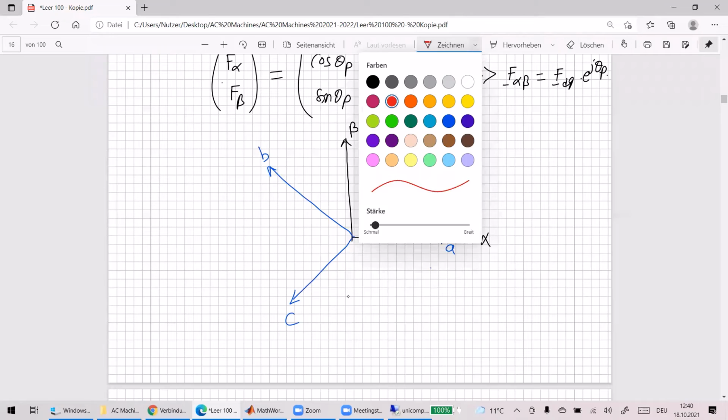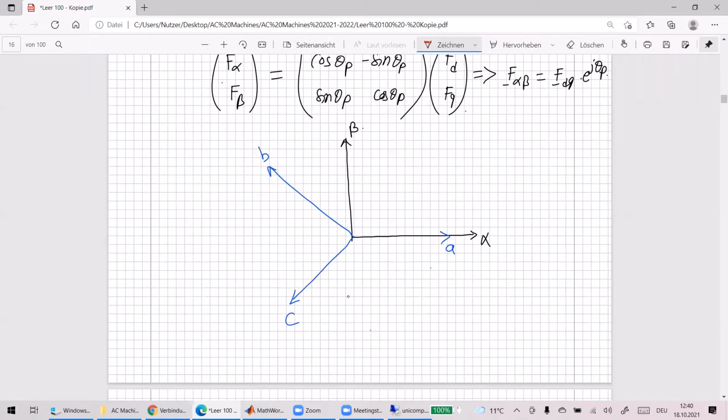And I also tried to show you that the resultant of ABC rotates anticlockwise for the positive sequence. For the positive sequence component, what we saw, our resultant vector is rotating anticlockwise, right? So let's say if this is a resultant vector, which is your v alpha beta. You can also write it as v with stationary frame superscript s. So it's just a notation. You can use any notation you like. And we know this is rotating with speed omega,